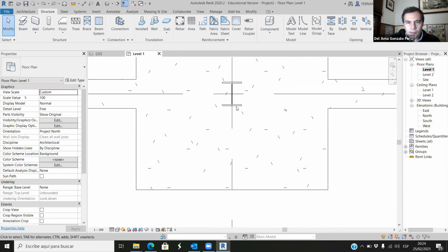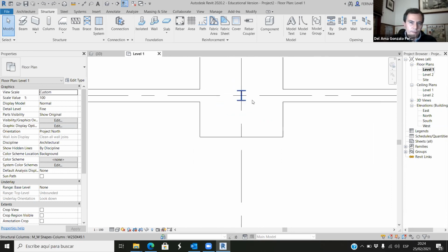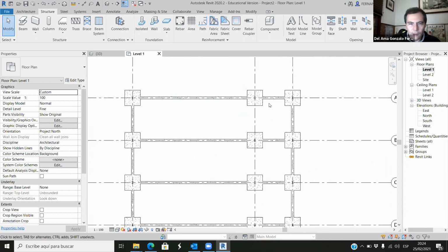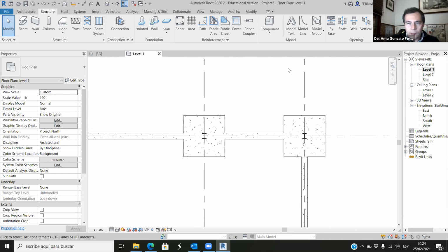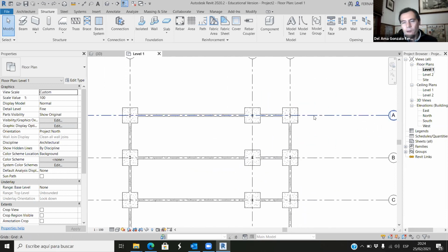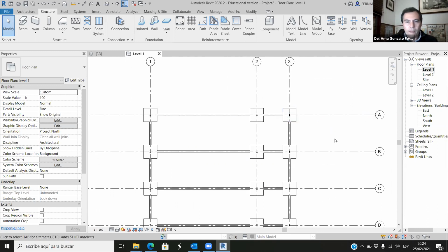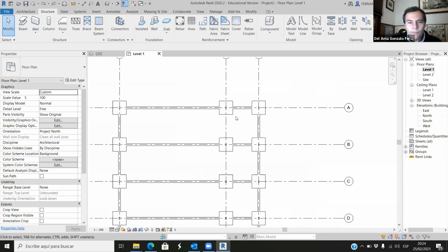If we are calculating structures, not only the shape, not only the amount of material or the size of that column, but even the orientation matters. In this case, if the wind is blowing in this vertical direction, that would be the right orientation. If the strongest wind blows in the other direction, then we should shift. Anyway.